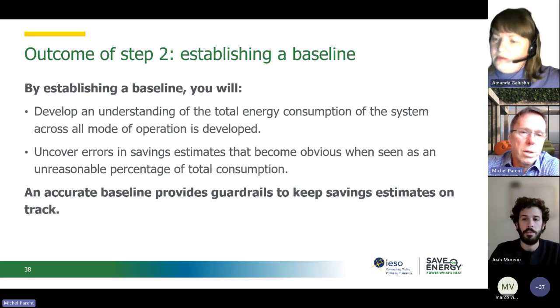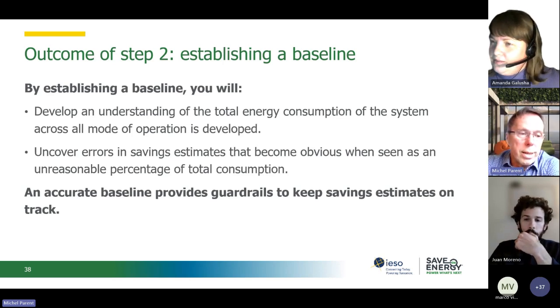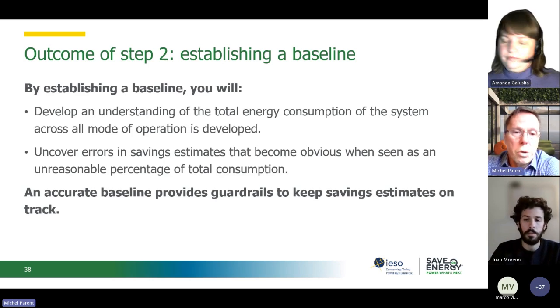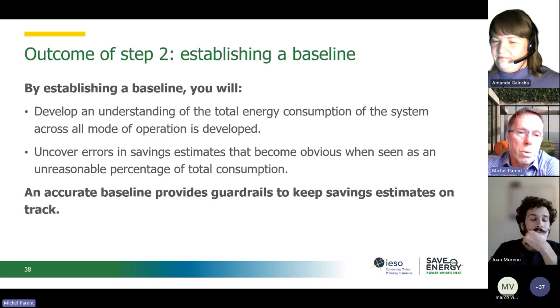Even though I did say 18 degrees C, you're right, Greg, it's all imperial. If you want to use the same equation in SI units, you replace the 1.08 by 1.2 and the CFM by liters per second and everything else in Celsius. But you're right, the heating degree days would be in degrees Fahrenheit.